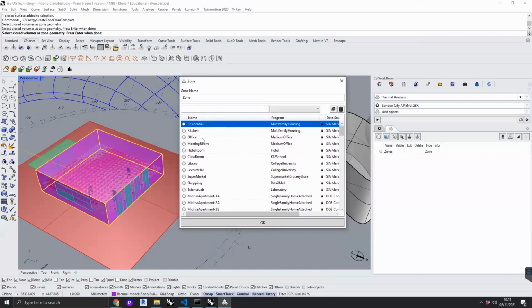And then once you've selected it, it's going to ask you what you're doing inside your building. And that's useful information because it's going to use that to say, how warm does this need to be? Does this need to be really cool in here? Is it going to be used all the time, or is it going to be empty some of the time? And if it's going to be empty some of the time, then maybe I don't need to heat it during the night or whatever it might be. If I say it's residential, then it's going to try and aim for, I think, something like a 20 degrees C average temperature all the way across the year. So it's just going to say there's always someone here, probably during the day and during the night, and I want it to be this nice livable temperature.